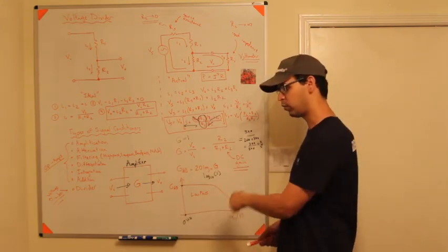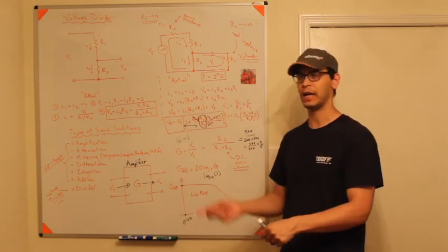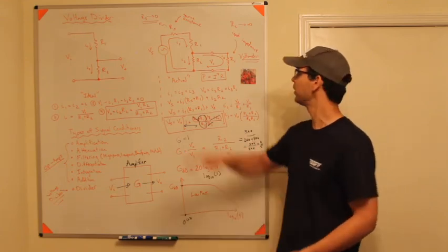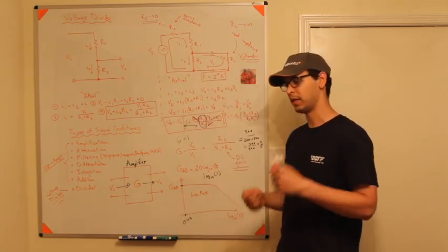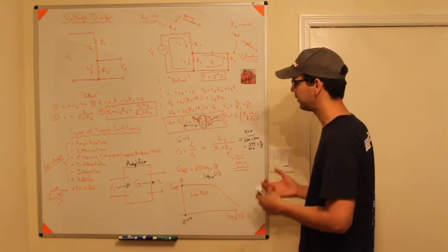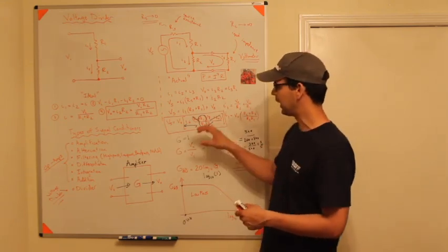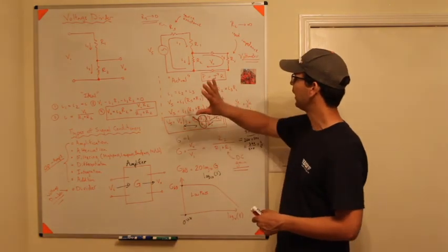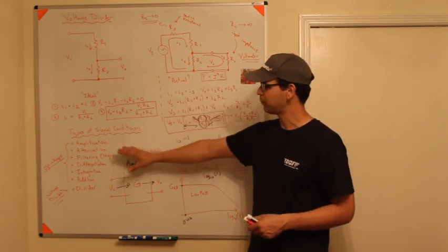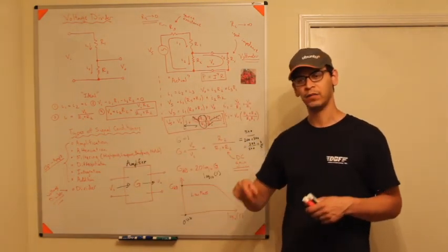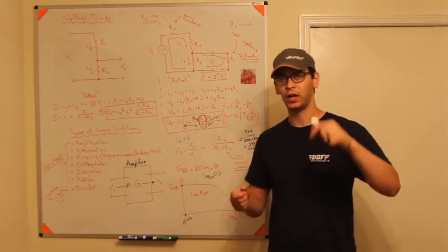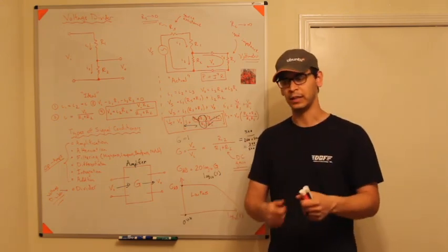Every time you plug something into a wall, you're adding resistance and you're creating more losses. You're probably dividing the current as well, but you'd like that resistance to be as low as possible. You want your source resistance to be as low as possible. And then if you're measuring the signal, you want that input impedance to be as high as possible. And again, I like this example because it highlights a couple things with gain and amplifiers and Bode plots and ideal versus actual. And a lot of this terminology we're going to use when we move to op amps, because op amps have a source voltage that we ideally assume is zero, and it also has an input impedance that we also ideally assume is infinite.